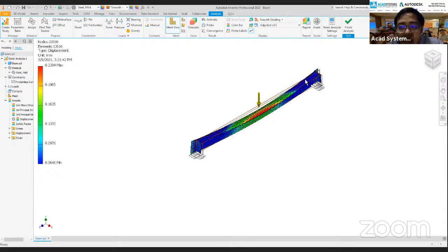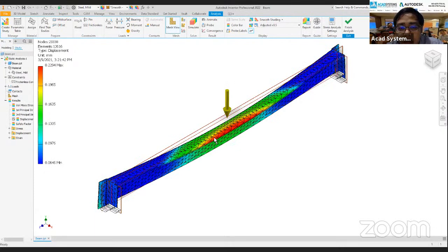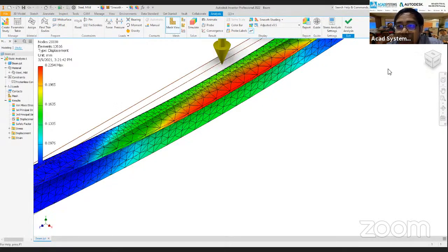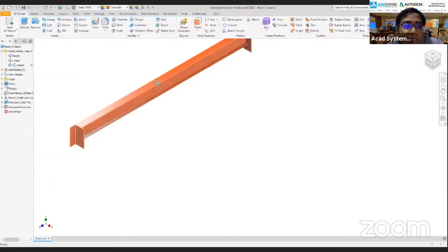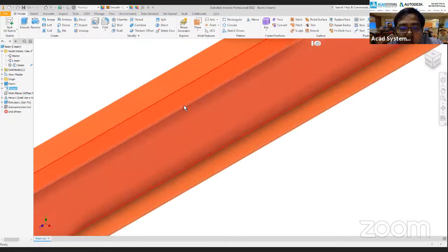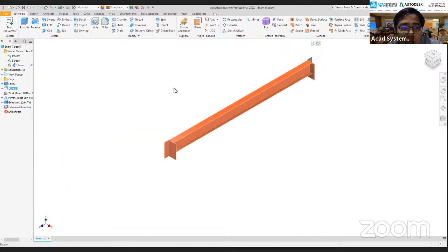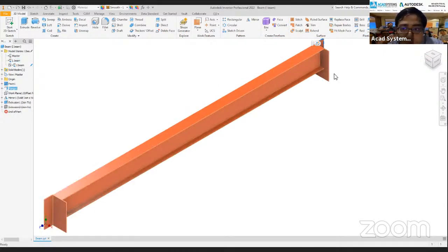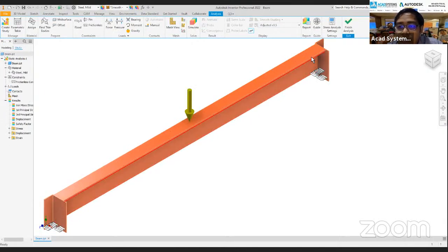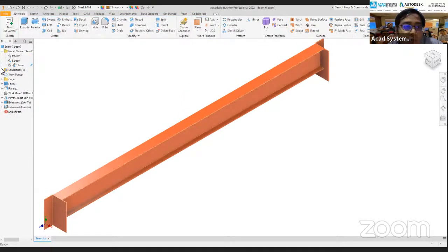For example, if you need to change the object, if I need to make this one much thicker, I can simply select finish analysis, and I can select this value and make this one thicker, right? Or maybe I want to select other types of beam. The one that I use over here is the L beam. So I want to use the I beam like here.